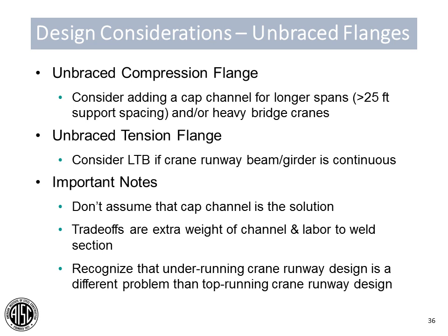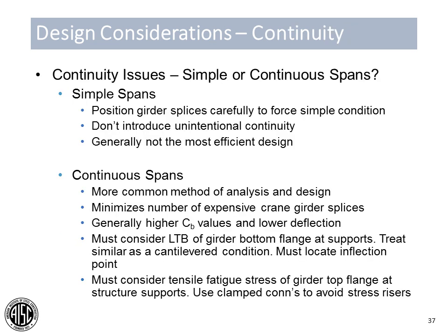We also need to recognize that the design of these underrunning systems is different than the top running systems in that the addition of a cap channel is not directly going to resist the lateral forces or greatly improve your lateral stability or lateral strength of the system. It actually is possible to hinder the overall strength of the system. We'll talk a little bit more about that shortly.